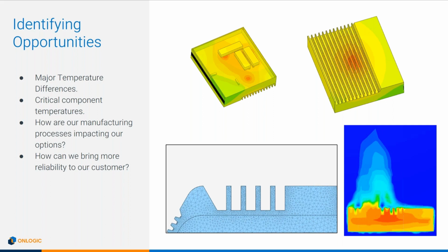In the bottom right of the screen, you can see a CFD simulation of some of the airflow and temperature around the system. By simulating the airflow around and over our system, we can make sure that, due to hotspots and different things going on inside of our system, we are getting the best airflow over our natural convection-based heat sink possible. Now, when I say airflow, I don't mean forced airflow. I mean airflow that's generated by the chimney effect created by hot air moving off of the heat sink.